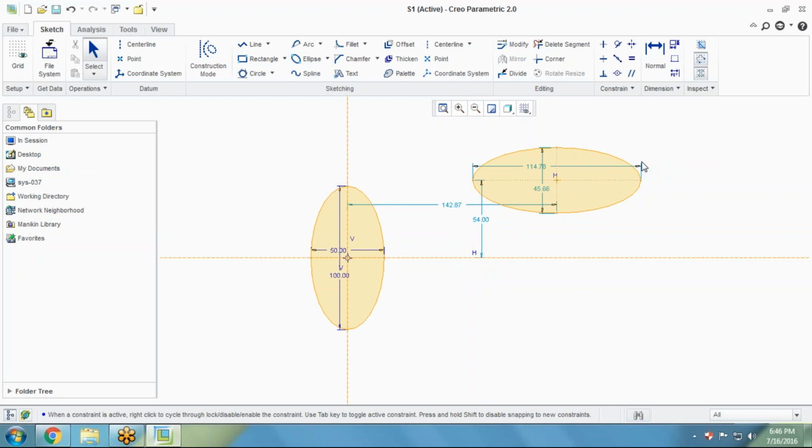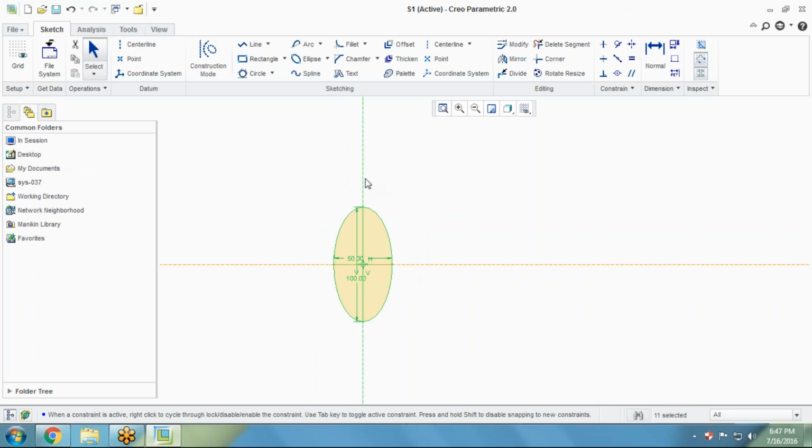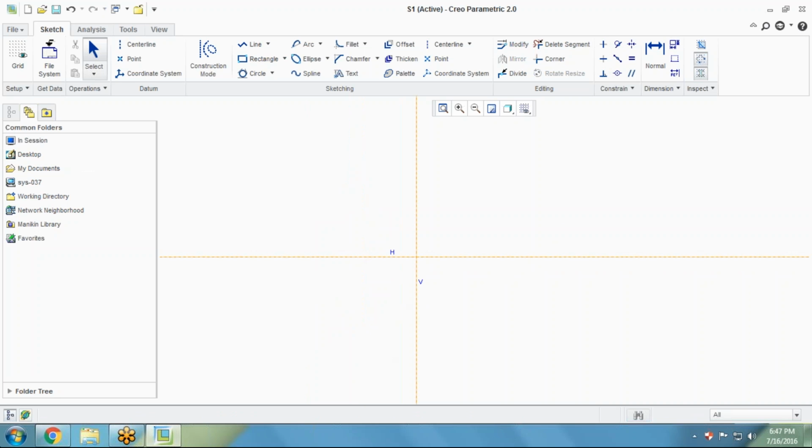So it is similar to that, but the basic difference is it asks for the center and extends at both sides symmetrically, whereas this one works on one point and a second point. So this is the basic difference between them. Here we have deselected these two lines and deleted the object, and now we have to specify vertical is this and horizontal one is this. So the degree will be deleted automatically.